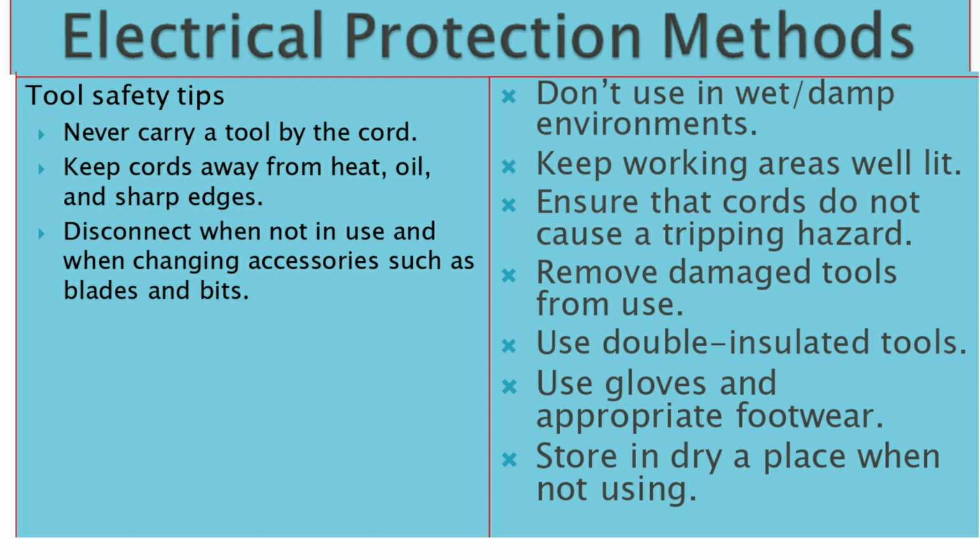Ensure that cords do not cause a tripping hazard. Remove damaged tools from use. Use double insulated tools. Use gloves and appropriate footwear. Store in a drier place when not using.